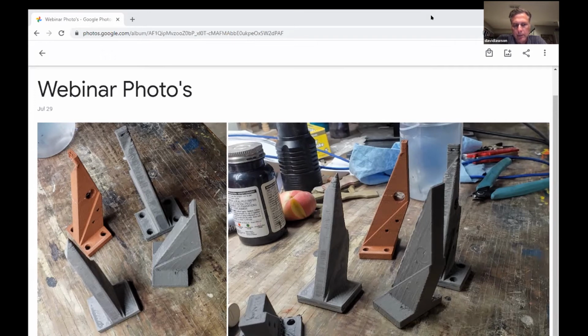In my experience, I have tried to create a thicker infill than the slicer programs give you. Because if I use the regular infill patterns and choose, say, 40%, my experience has been that when I go to sinter that, I get a collapsing of the infill on the internal sections of the part.